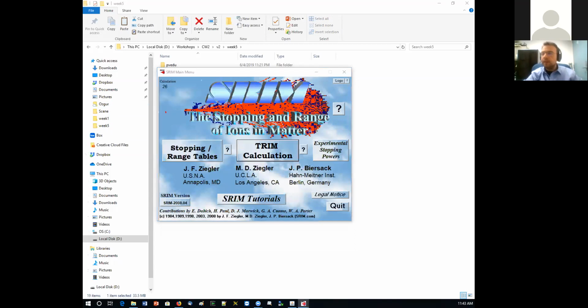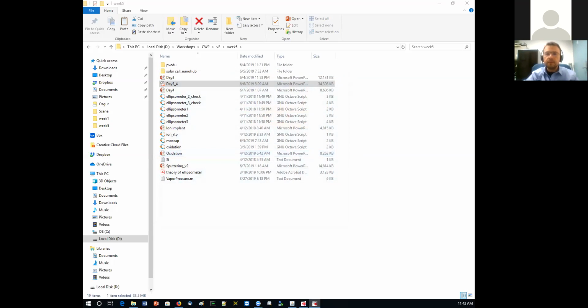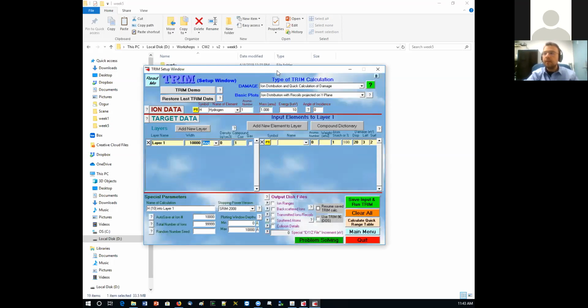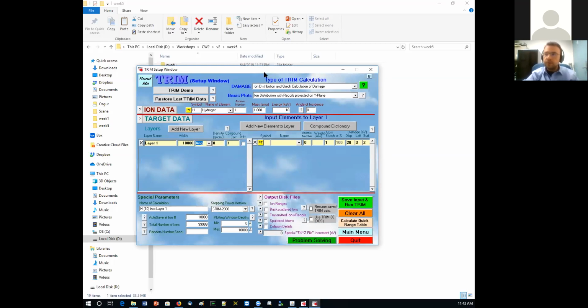So we would like to see the demonstration of the light ion and the heavy ion, right? Let's do that because we don't have the time to carry out the whole computation. So let's just go to the TRIM calculation. I am using 2 monitors, that's why it's immediately disappearing. Now here, we will do 2. The first ion that we will send is going to be boron. So come here to where it says PT.